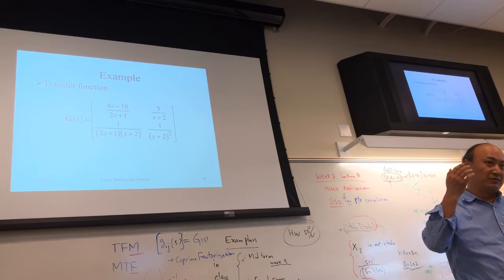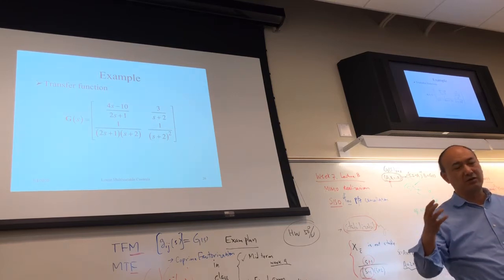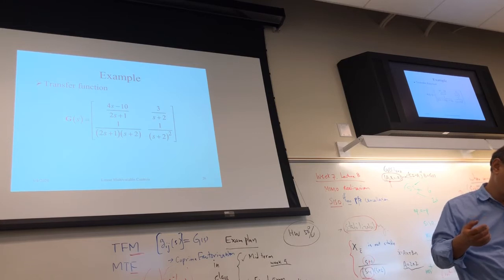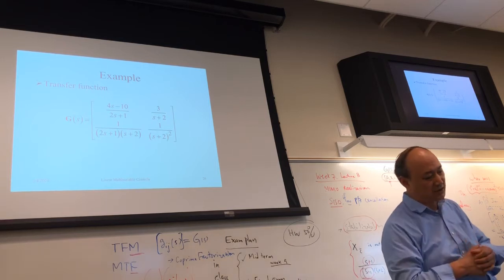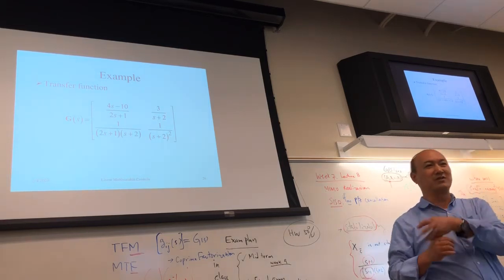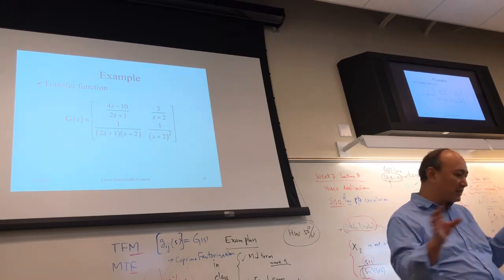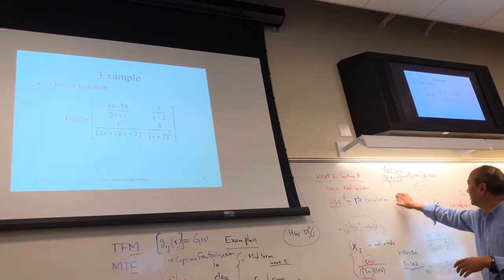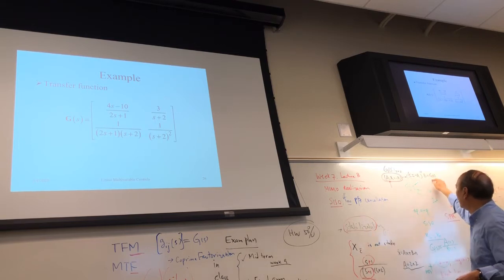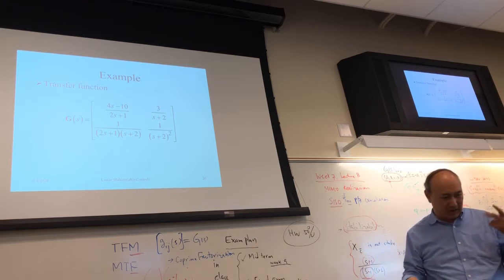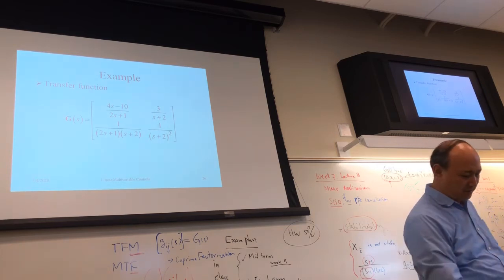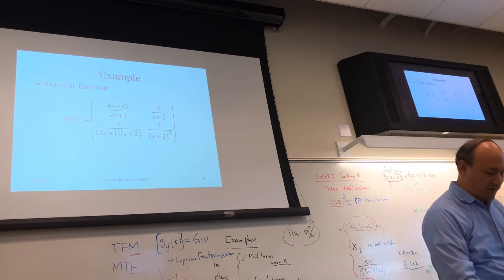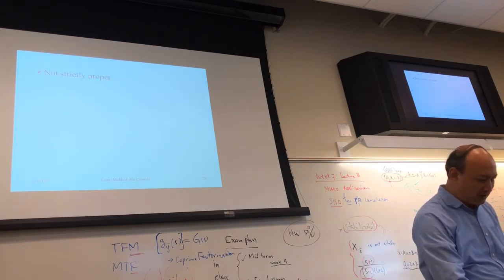This is the generalization of the SISO controllable canonic form or observable canonic form. So at least it guarantees controllability if you use the controllable canonic form, but observability is not guaranteed. Or you do the observable canonic form, but controllability is not guaranteed. But it doesn't matter, because you can always make this one into this one. That's always possible, always correct. But it may not be both controllable and observable. We're going to solve this problem next. It's called minimum realization. But let's just do one interpretation here.